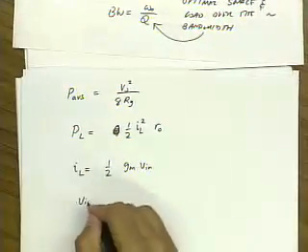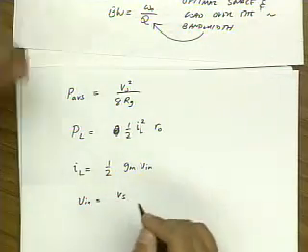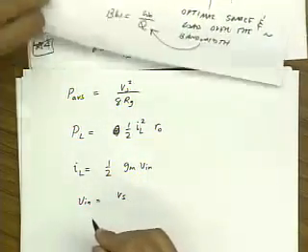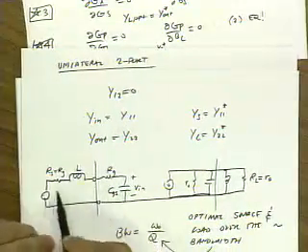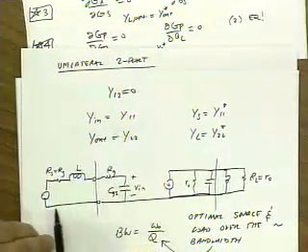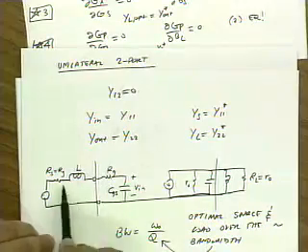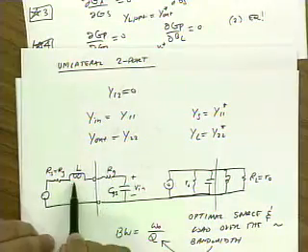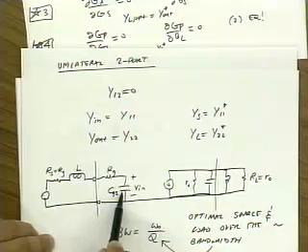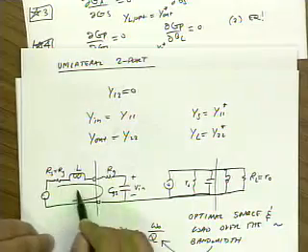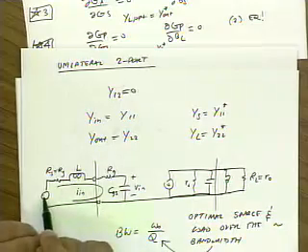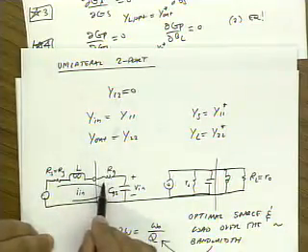Well, it's a series resonant network. So V in, which is here, is equal to this voltage divided by this series RLC impedance. Well, again, at resonance, this cancels out with this. So V in is this current flowing in this loop, I in, which is simply Vs divided by 2Rg times this reactance.